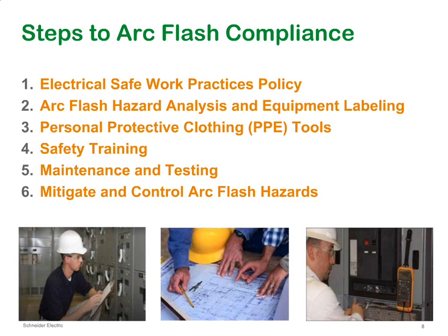Then safety training needs to be provided. This is basically a requirement in OSHA and in NFPA 70E that the workers must be qualified. What is meant by a qualified worker is a person who is familiar with the equipment that he is working on, and he is also familiar with all the safety procedures and processes laid out by OSHA and NFPA 70E. So that training essentially gets the worker through those items written in the electrical safe work practices policy and through some basics of safety protection, and that's typically done in an 8-hour class with somebody who has the knowledge and the experience to impart that knowledge to the worker.